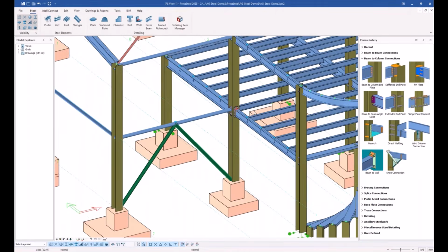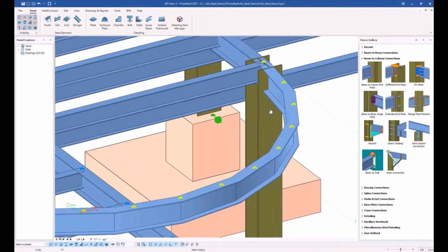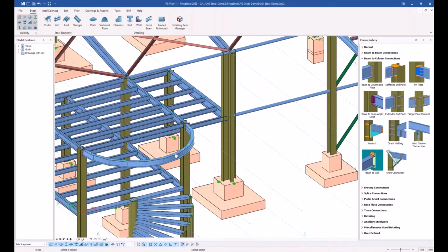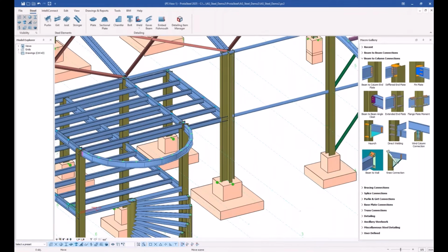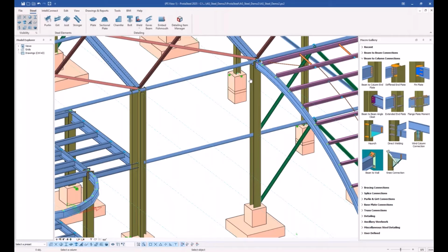And another new feature is that we have brought the support of curved beams end plate connections. So I select the beamed column end plate, select the column, curved beam here, and right click. Column, curved beam. There's a visual glitch here currently. It is just a visual thing, and we have already fixed it actually. Let's do the same for the vertically curved beam, like this.